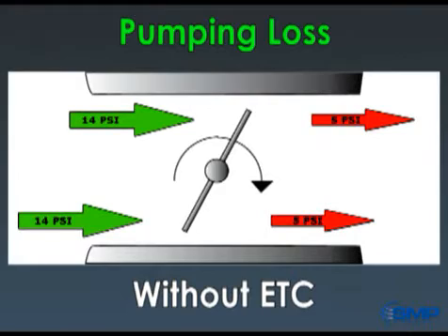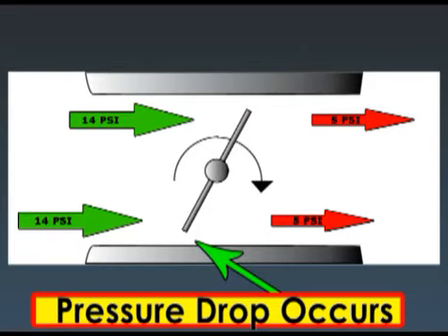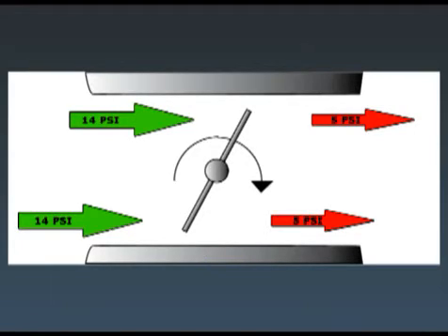The major cause of reduced engine efficiency at low engine RPM is pumping loss. Traditionally, reducing the output of an engine is accomplished by limiting the airflow into the engine. The throttle plate restricts the intake of air by forcing the engine to drag air through a narrow or restricted inlet. Restriction of the air intake creates a pressure drop across the throttle plate. Most technicians refer to this as intake manifold vacuum. Since the air entering the cylinder is now below atmospheric pressure, less air enters the cylinder. On a speed density system, the engine control system measures the pressure differential and reduces the fuel input accordingly. The reduced quantities of air and fuel result in the desired reduction of power output.